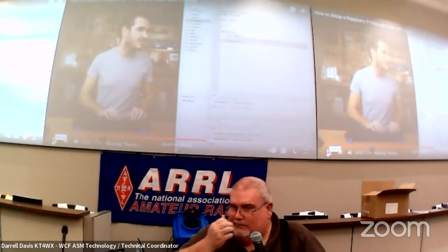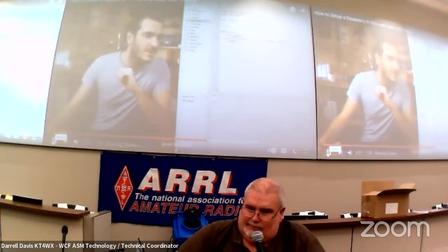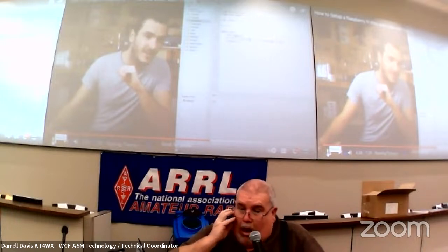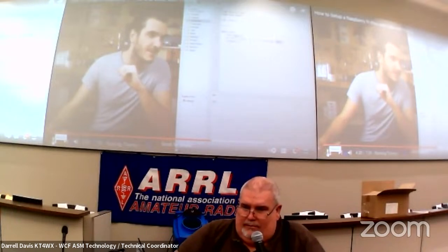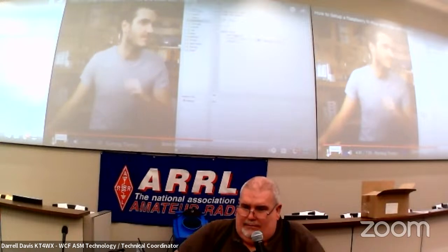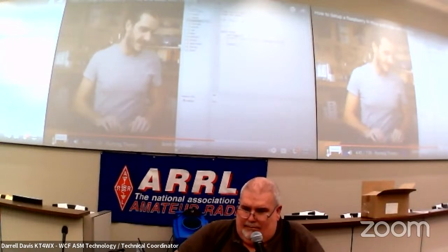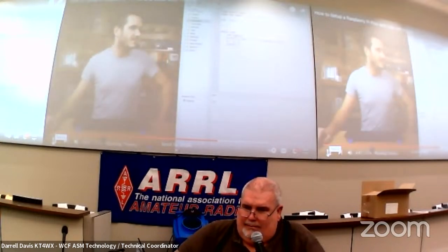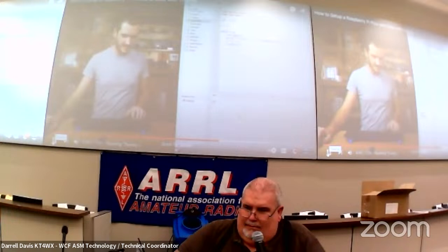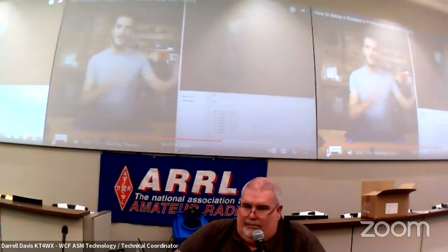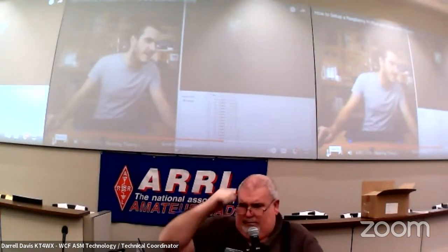The order that you put arguments in here will matter. The first argument will go in this first place, and the second argument will go in this second place. And finally, we just need to increment n. n equals n plus 1. Save that file again, and Control-D for a soft reboot. And there we have it. We have a blinking LED, and we also have some nice printed commands on the screen.